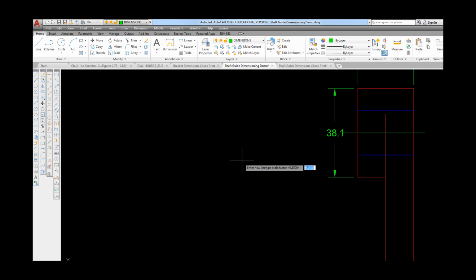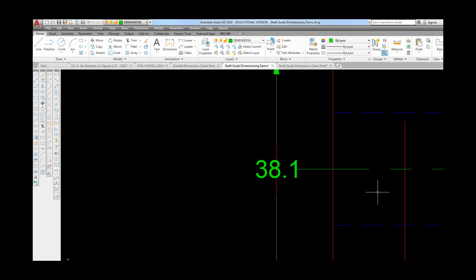Well, I don't see anything on that one, so I'm going to see, let's see, it's actually set to 0.15. Let me do an undo. I just want to see what that was set to originally, just make sure I didn't misread that. LTS and enter. Okay, yeah, it does say it's 20. So I'm going to type 15, not 0.15. There it goes. That actually worked.